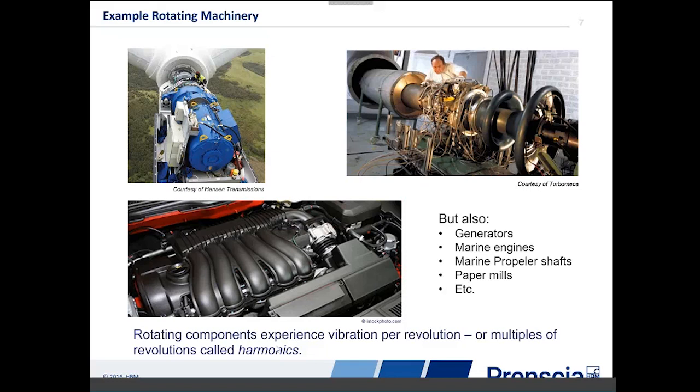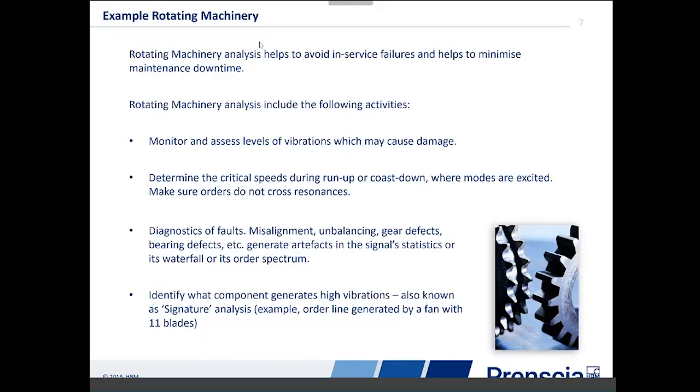So basically here we are considering measured data. You've got sensors, typically accelerometers, but there's nothing stopping you from using strain gauges, microphones, any sort of sensor that's able to capture the vibrations and the mechanical phenomena resulting from an operating engine or component, right? And another input we need for this type of analysis is the RPM profile.